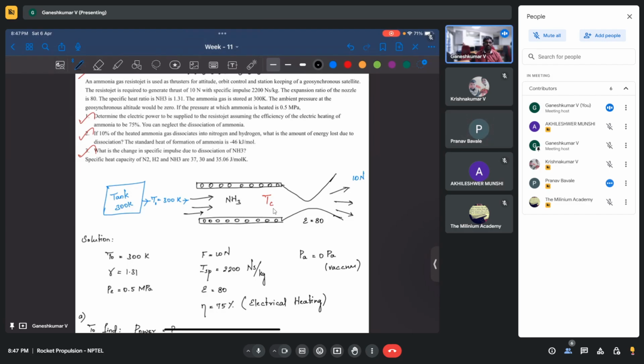What you will also have is, because of hydrogen and oxygen, the temperature can reach higher. Now you have reached only 1400 Kelvin. You could reach 2500 Kelvin. That is a huge increase in temperature, compared to the increase in CP, which is going to affect your performance. Whether you will have that much increase in temperature is also a question, right?